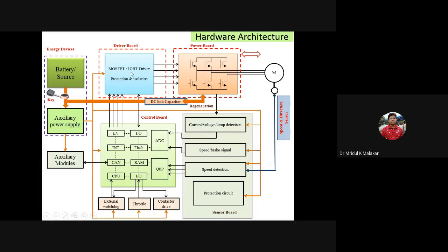There is the high power application. It is the main power board, meaning the inverter. This will drive the motor. To drive these MOSFETs or IGBTs, you require some driver. The driver is needed because the controller is a low power system.